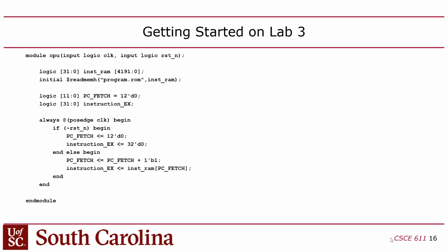So we're going to issue 1 instruction per cycle here because there's only 32 bits coming out of the instruction RAM. So we only have the ability to read 1 instruction per cycle, which is going to ultimately limit the speed of the processor, the throughput, how fast we can churn through instructions. Okay? So we're not superscalar. No, not unless you're getting graduate credit. Lab 5 is the graduate version where we're going to expand it to have 2 instructions pop out.